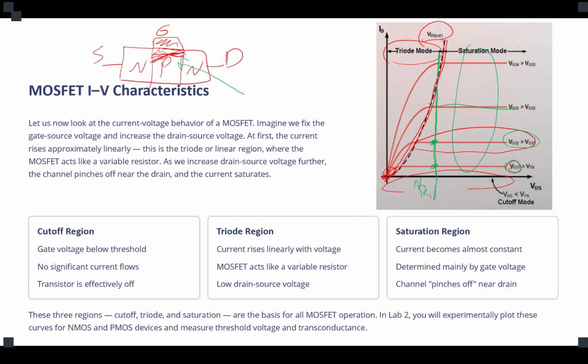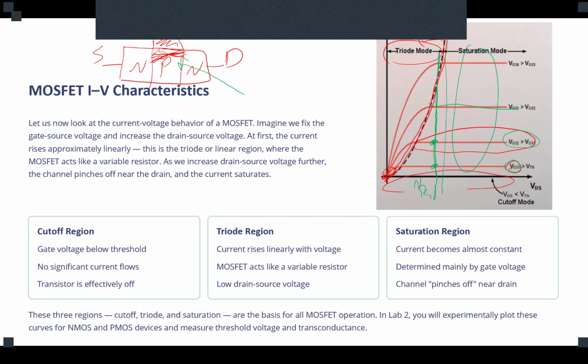Is that clear? So two reasons. One, the fluctuation and uncertainty of the voltage between drain and source. Another one is the thermal effect. So we want to keep our MOSFETs in saturation mode, far from that region. We don't want it to be near this curve of VDS saturation. We want it to have a proper distance from that point.